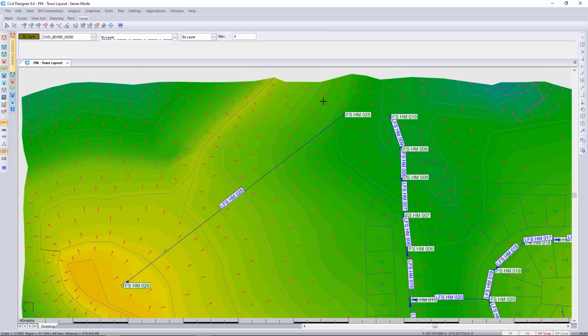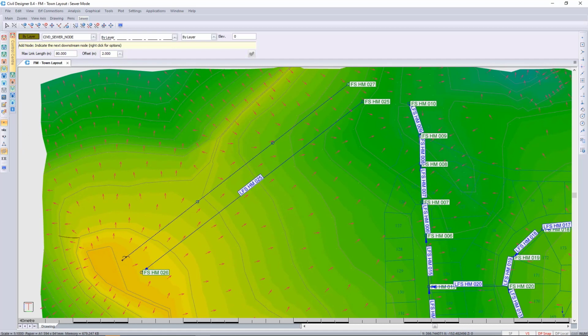However, with the new method, if I press escape and spacebar and we set the manhole spacing, immediately you'll see your equidistant spacing of the manholes. So this can really benefit you in saving you time for when you're doing your bulk lines.